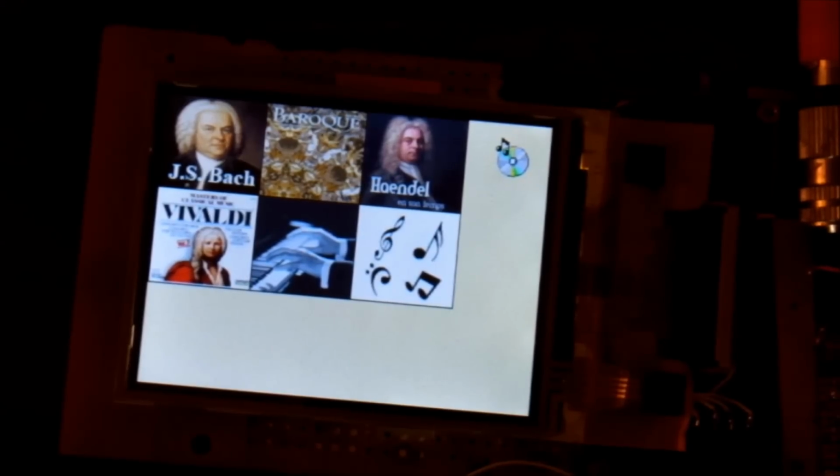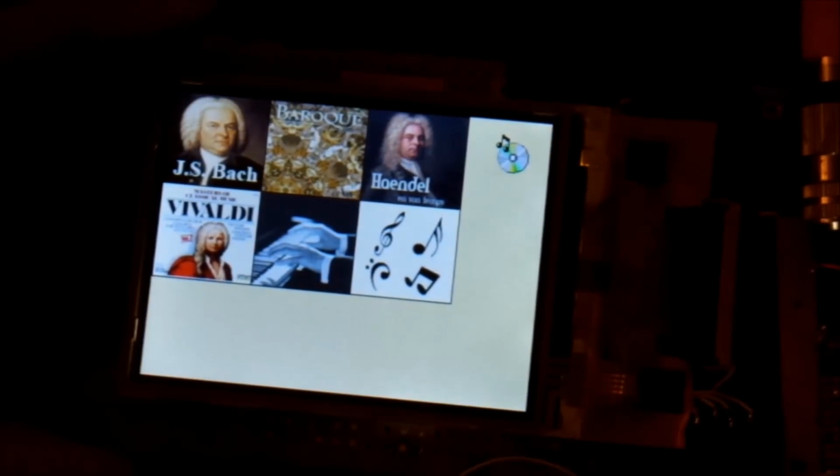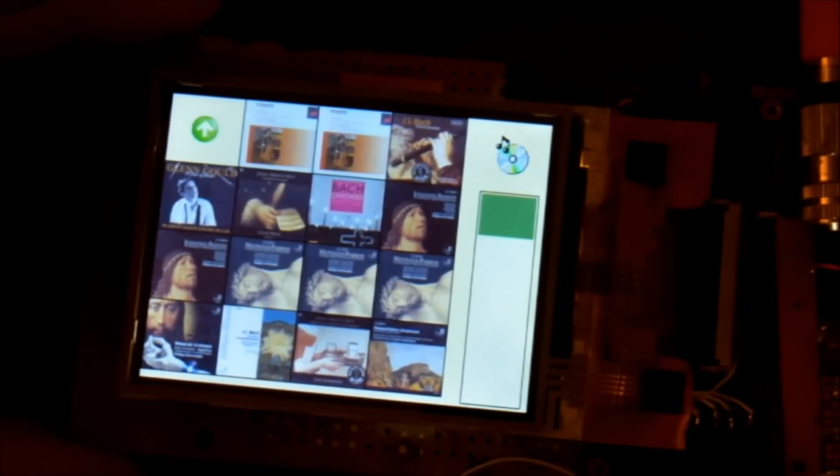As I said during the presentation, the user interface is 100% managed code, pure NetMF stuff, and the screen is completely regenerated on each update. Here there are 16 bitmap image files read from the SD card each time, and the complete screen is dumped to the TFT graphic memory in about 3 milliseconds. There is only one SD card, so both CPUs compete for it: FreeRTOS when playing the WAV file, NetMF when reading bitmap images.